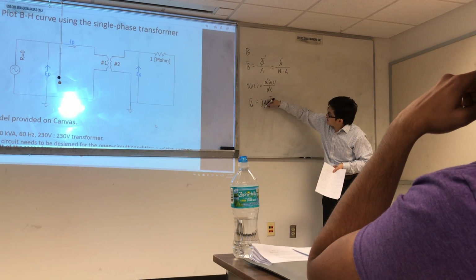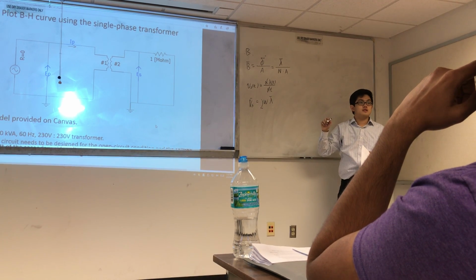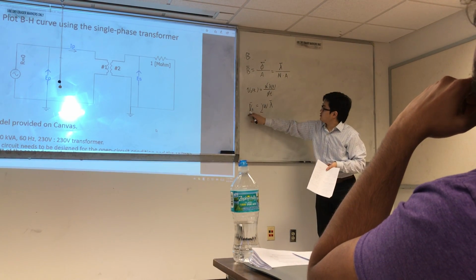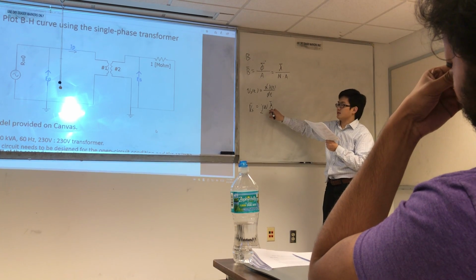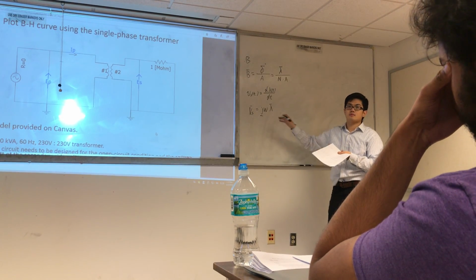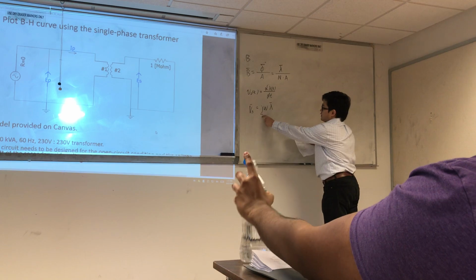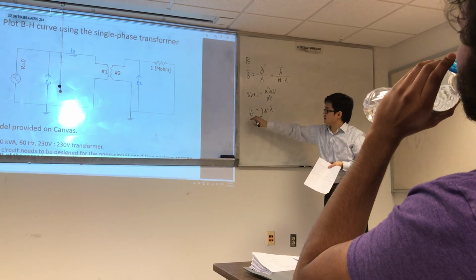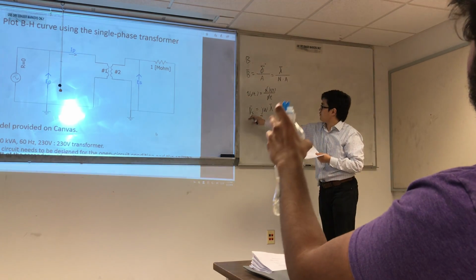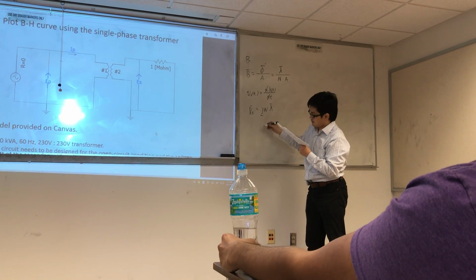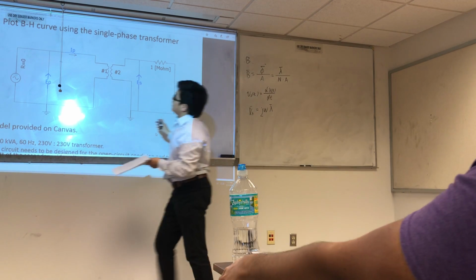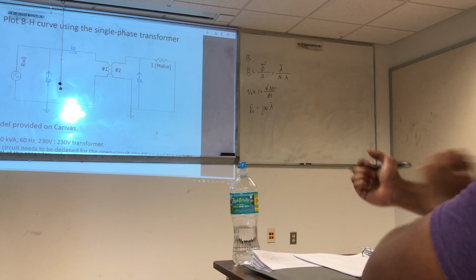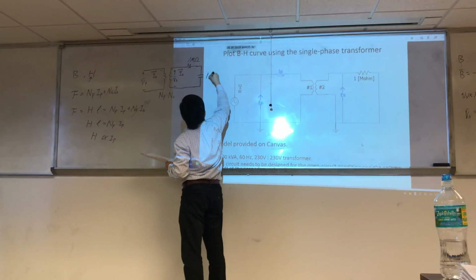Yeah, but you can see there's a phase shift. There's a j there, so there's a 90-degree shift here. That means Vs is always leading lambda. So we need to make them in phase, so reduce the angle for Vs. How to do that? We need to add a capacitor here, a small capacitor, like 1 microfarad.